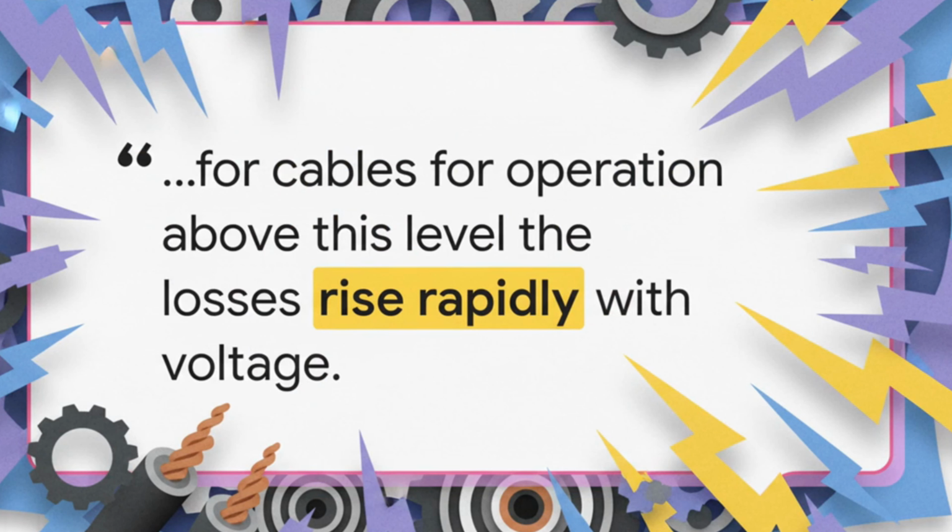Now, this is absolutely crucial. While conductor losses are usually your biggest problem at lower voltages, these dielectric losses, they become a huge deal in high voltage systems. As you can see from the quote, as that voltage climbs, these losses just take off, rising super rapidly. You absolutely have to factor them into your designs.